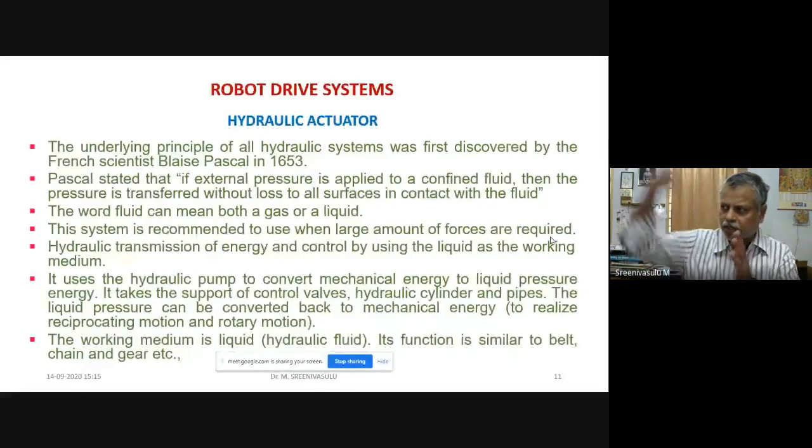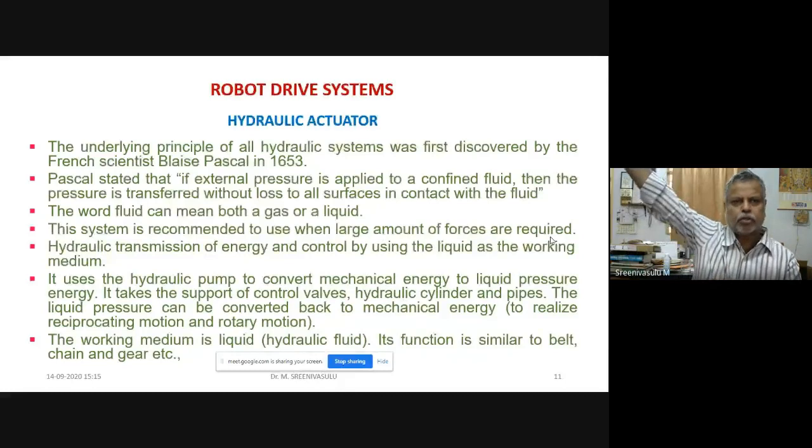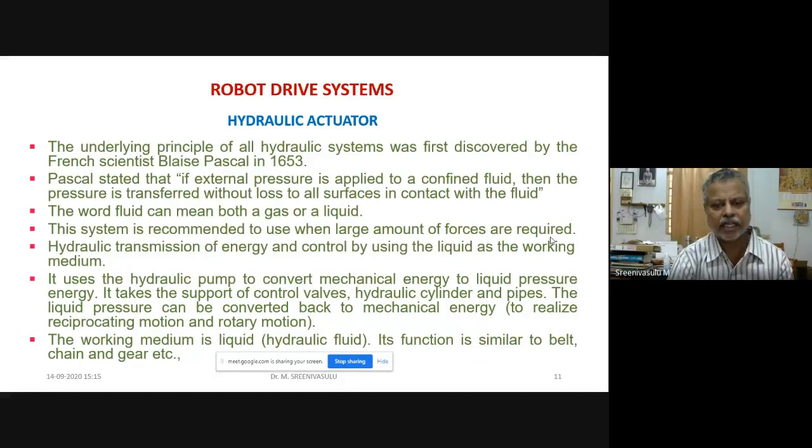Tractor, when you want to lift the trailer, what they try to do is, it appears as if a gear has been engaged and disengaged. One lever they apply, then they accelerate. That will activate the hydraulic pump, and that pressurizes the hydraulic fluid that contributes towards the trailer rising up. That is how it is actually happening over there.